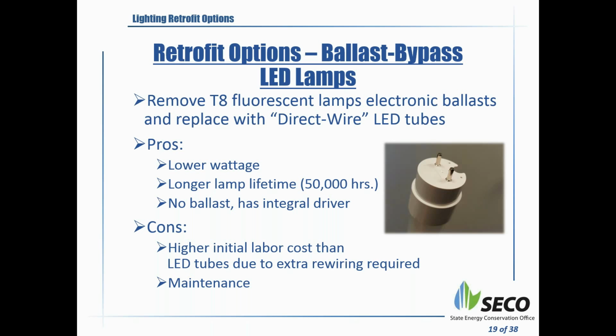One of the concerns is that now you don't have a ballast. So when you are doing long-term maintenance on this project, when you rewire it and put this in the same socket, you need to know which socket is hot wired. There will be one socket that will always be hot wired, with 277 or 120, whatever voltage you have, coming to that socket directly. So that's something you'll have to watch out for. And normally, people are still working on the nomenclature and how to identify them and what the retrofit options will be, and so on and so forth. Question.